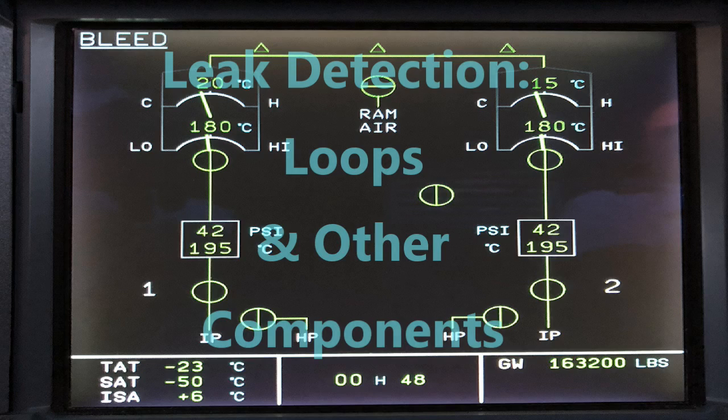So those are your threshold temperatures, where it's like, okay, that's getting too high, and that's when it's going to start sending those signals. And just a tip here: let's say a leak is detected, then that leak will close associated valves. It makes sense. Those valves are automatically controlled to close if they were open.